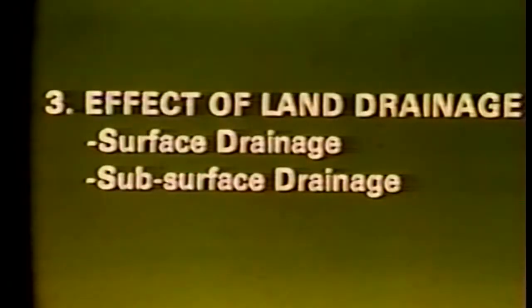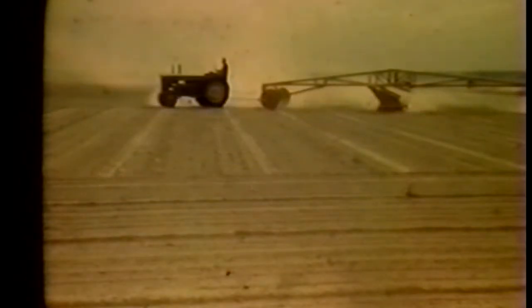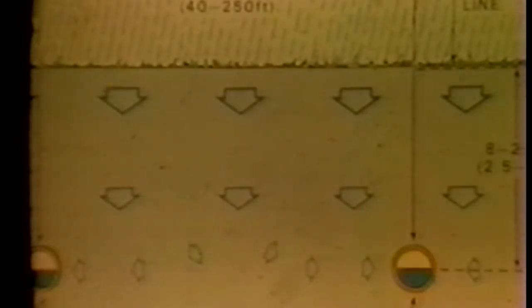2 types of drainage systems are used to remove excess water from a field: surface drainage and subsurface drainage. Surface drainage is accomplished by land grading, land planning, or constructing shallow open ditches and waterways. A subsurface draining system is a network of ditches or buried drain pipe, usually corrugated plastic tubing. It is installed at a sufficient depth to intercept and carry off excess subsurface water. Both surface and subsurface drainage systems may be needed.